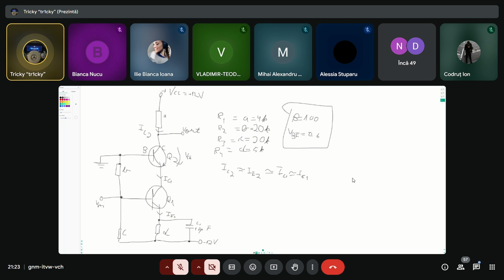Yeah, I'm pretty sure we could take this Kirchhoff over here, all the way to minus 12 volts. And this will be equal to VEE, which is equal to R2I plus R4I. The current will be equal between them as they are in series.